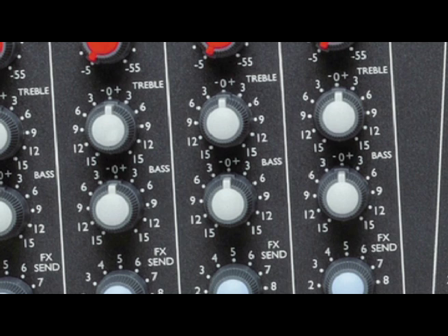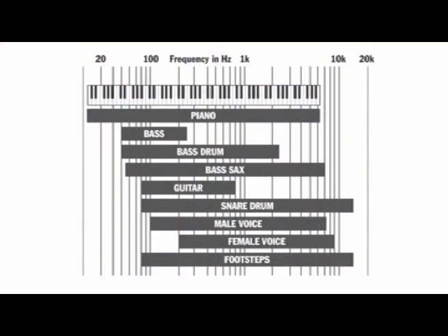There's a drawback with fixed EQ, which is that if you want to work on a particular sound, the punch of a bass drum or the ring of a cymbal for example, you won't be able to focus the EQ on the exact frequency. In fact, you can only boost or cut a pretty huge part of the audio spectrum, and you'll end up changing much more of the sound than you might want to.